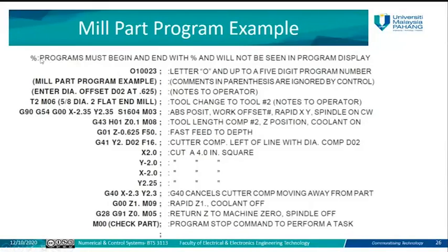Okay, so the first thing in this milling part program is the sign which the program must begin and end with. If you see this percentage sign, it indicates the beginning or the end of the program. For the ideal structure of programming, you should start your program with this percentage sign and end with the same sign, at the beginning and at the end of the program.